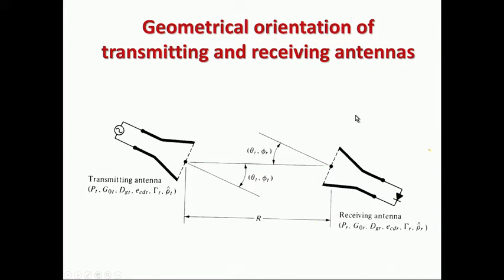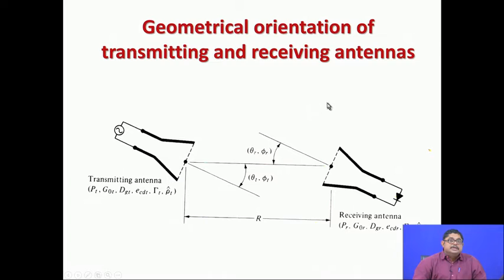Now, apart from pattern, we will see what the interests are. Actually, in analysis techniques we have seen that from a radiation pattern we try to find out the 3 dB beam width. If we get beam width in two principal planes, from that we can make estimates. But another important parameter is finding gain.